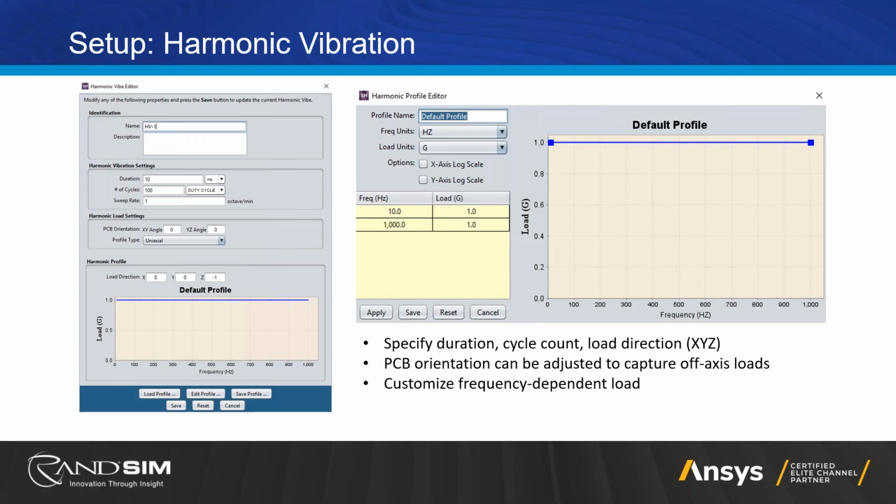So if you have a certain frequency that you're operating at, or that your environment's going to be impacted by, so maybe for example, if this is going to go on an aircraft, there's a profile of the harmonic frequencies associated with the airline engines, and so you could run a harmonic vibration analysis at those different frequencies at various loads to understand what that might look like in your end result.